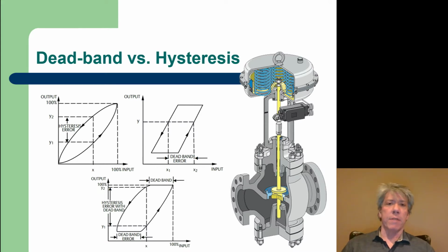There's a paper I found that I've posted in Brightspace by Fisher Controls, which I believe was either bought by or merged with Emerson's, because it has Emerson's name on it. Fisher Controls, if you're not familiar with them, have made control valves for quite a long time. They're a good control valve, and basically they are pneumatically operated valves for controlling fluid flow. You can see one in cross section here where the diaphragm is at the top. You can see the springs for returning the diaphragm to one particular position, and therefore the stem, because you can see the yellow stem connected from the diaphragm actuator all the way down into the body of the valve.